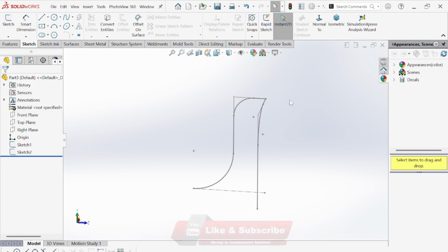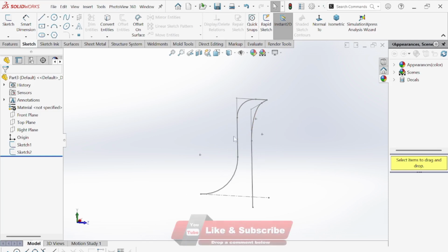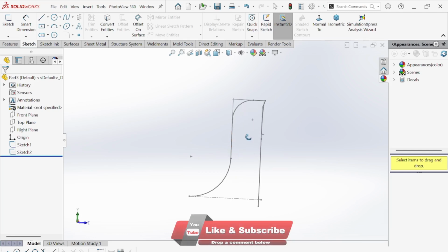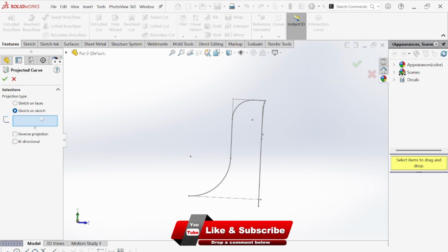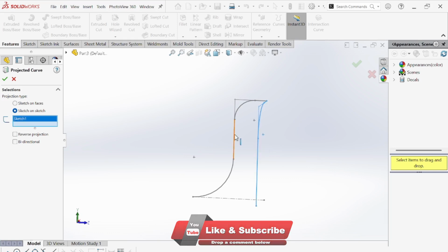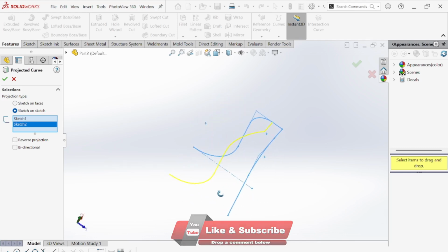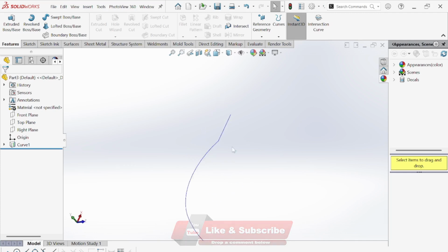Now we need to do one more thing. We need to put this sketch on this one, right? Because we need to make this sketch as per this sketch. So simply go to feature. Here in the curve option you will get projected curve. Simply sketch on sketches. First you have to select this sketch, and select this sketch. Now here you see it gets projected, and make this okay. Now here you see there's something wrong, but no, it's fine.